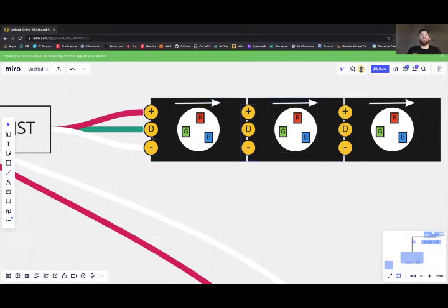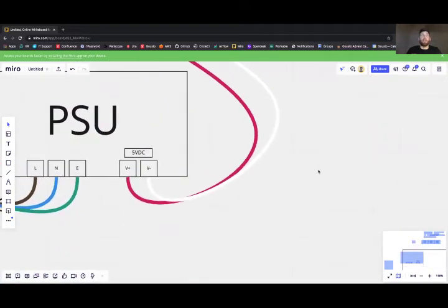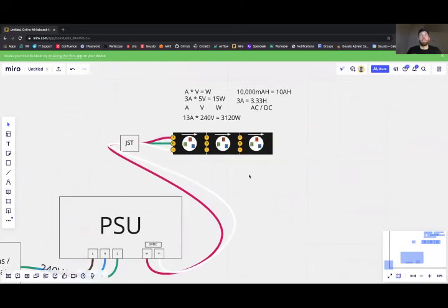So at each junction, your current has the option to pass through this emitter, this pixel, this integrated circuit, or carry on. Then it has the option to pass through this one or carry on, and this one or carry on. When it passes through, the current connects back through to this negative wire and goes back to the power supply and completes the circuit.